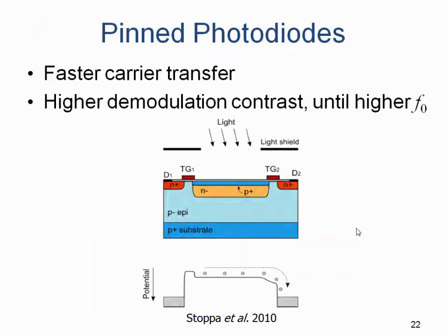Now, why change this approach? Well, actually what David did, he did something clever and introduced a concept that is known as PIN photodiode, which is well known in the imaging community, and is usually used to make sure that you can transfer completely the photo charges that you have detected into the junction here, thereby eliminating charge sharing.